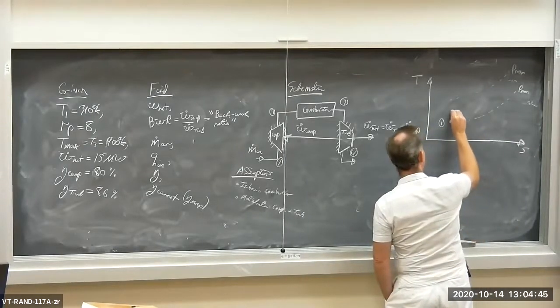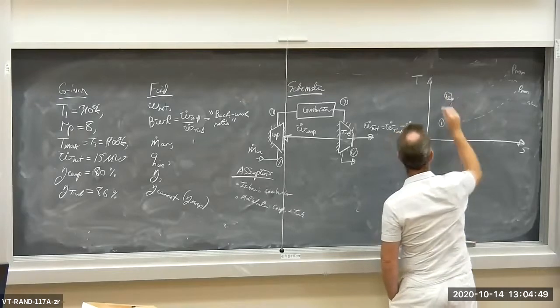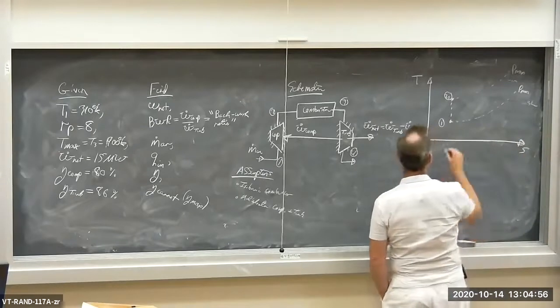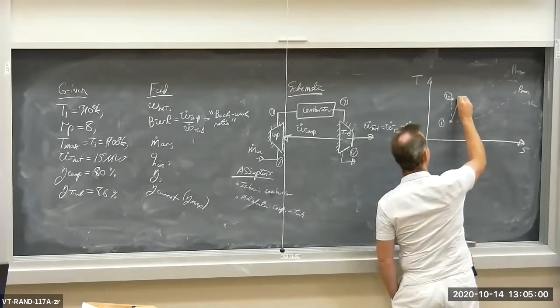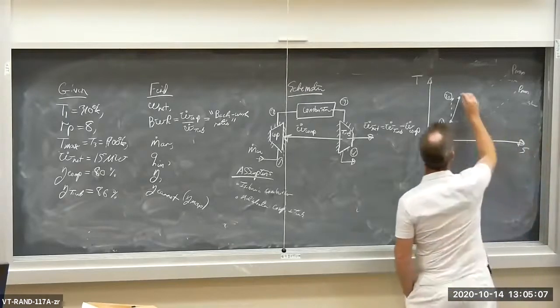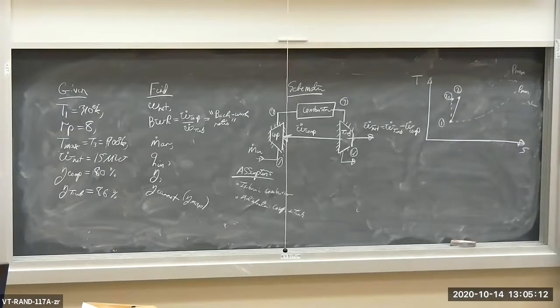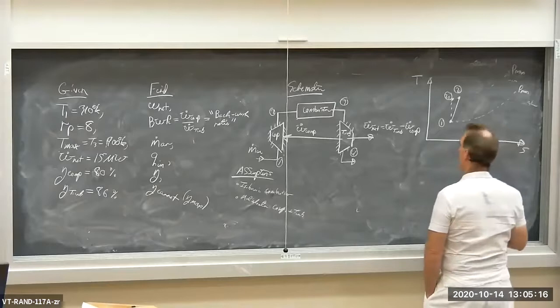The isentropic process, if this were an isentropic compressor, would be state 2s. Sub s means constant entropy. But we have an isentropic efficiency less than 1. So we're going to have some irreversibility inside of the compressor, and therefore some entropy generation, and therefore a delta S within the compressor. So this is state 2, an increase in entropy from state 1 to state 2 because we have irreversibilities occurring inside the compressor.